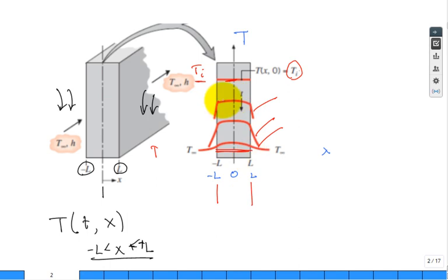All right. What about right here? Where is it hottest? After some time, it's hottest right in the middle, like you would expect. But what about the surface temperature? Doesn't it look pretty close to the center line temperature? Sure. How about at this time? Maybe this was 1 second later. Maybe this is 3 seconds later or 3 minutes later, whatever the time scale is. Now, what is the center line temperature? And then this is the two surface temperatures. Aren't they about the same at that later time? And then we come down here. Center line, surface, aren't they all about the same? What are they showing us? That basically, if I check the Biot number for this problem, it would be much less than 1. It's small. It's a small Biot number. It's basically our concept of uniform temperature in our slab. Okay, you understand that plot?